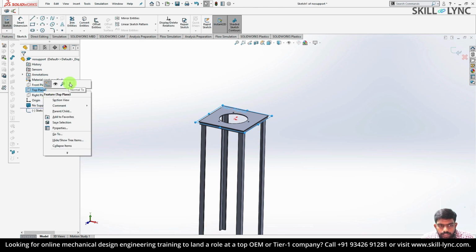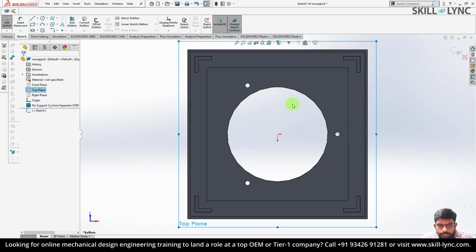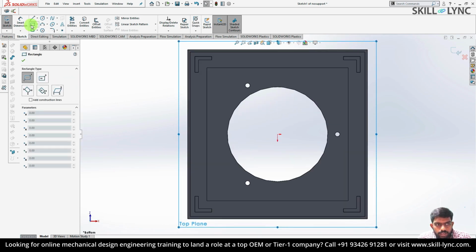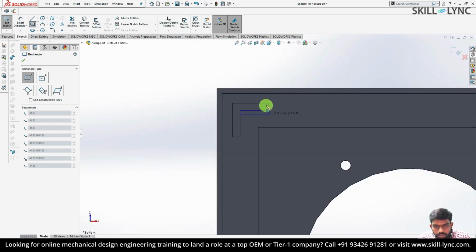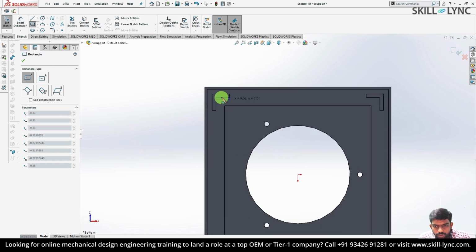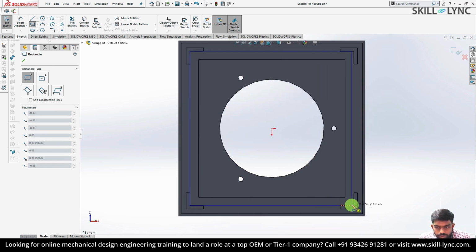Afterwards, choose the normal to option to view the plane in a perpendicular direction. Here choose the rectangle drawing options and click on the corner to corner method to draw a rectangle. Make sure you select the point exactly so that your stiffener is in contact with your legs, else you may end up having a discontinuity between the stiffener and the Cyclone Separator legs.